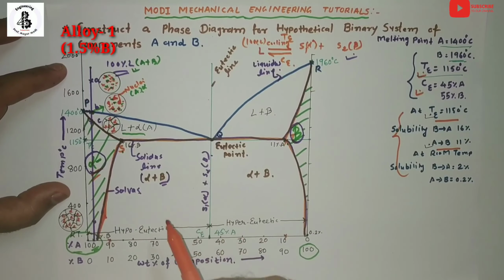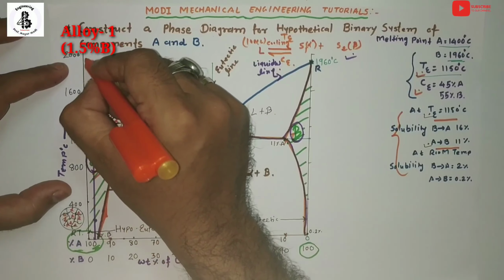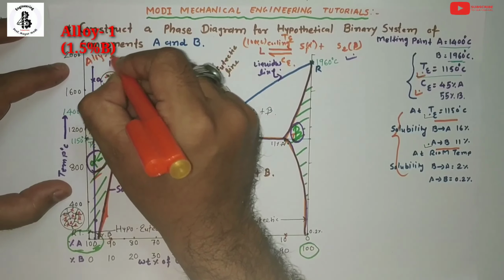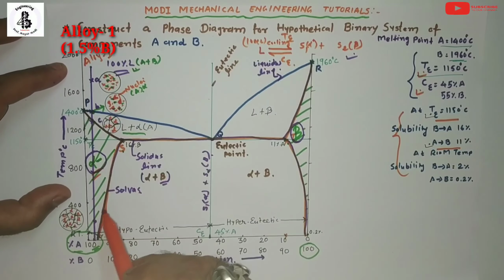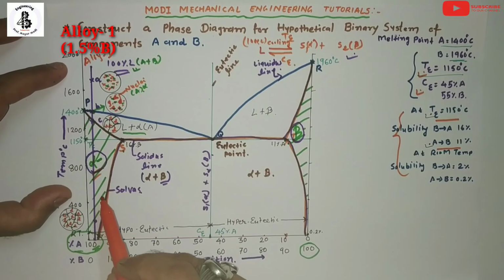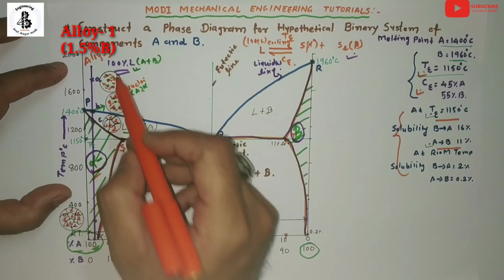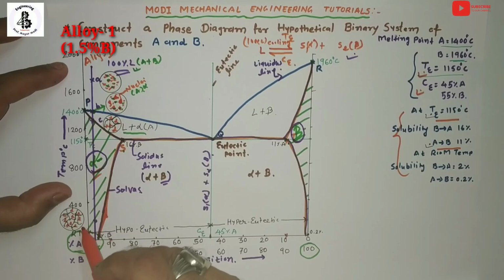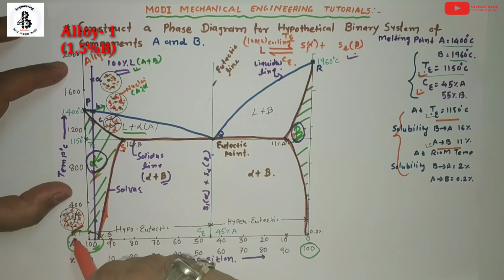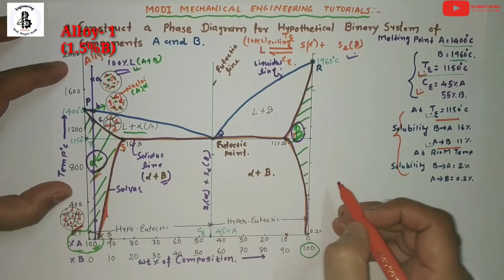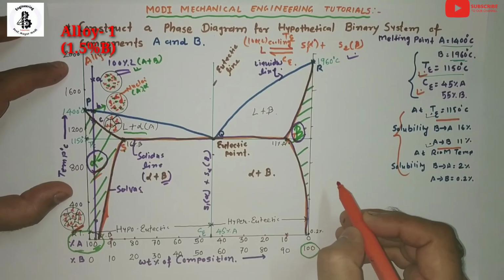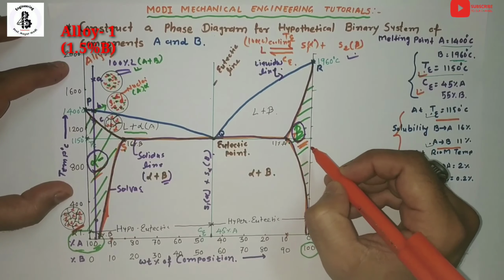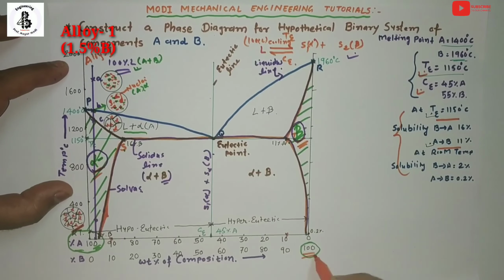The important thing for this alloy, or you can say alloy number 1, is that it is in the region of 100% solubility in the liquid state as well as in the solid state, which forms a single phase solid as alpha. Similarly, you can also take the region from the other side for a single phase beta, because there will be the enrichment by the metal B.